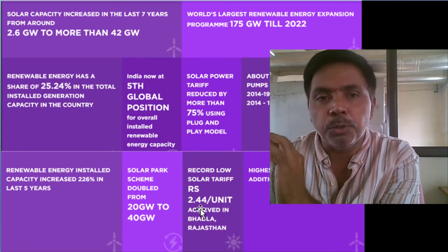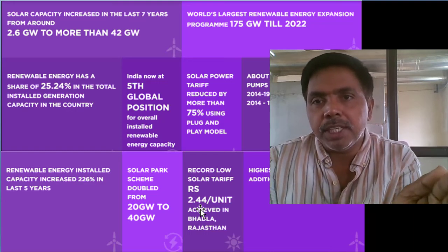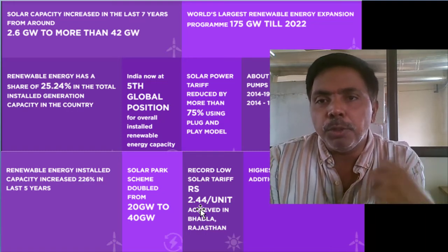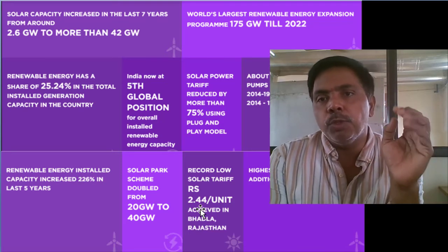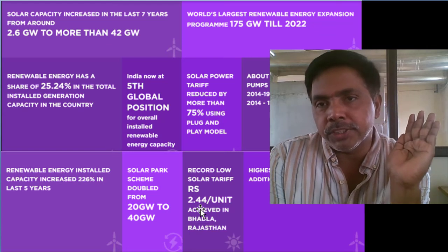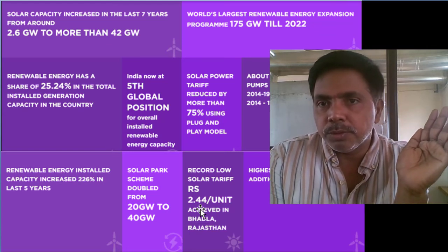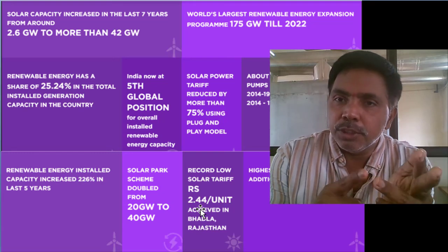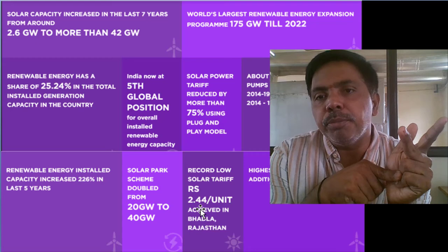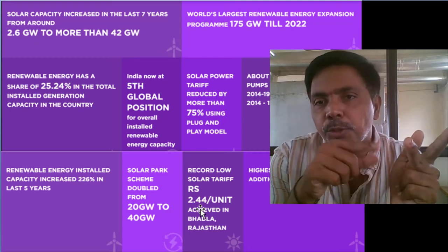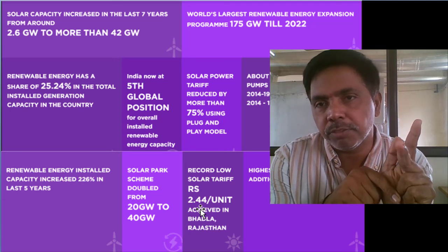Solar PV efficiency is low. Why? Because the semiconductor is unable to utilize the infrared or ultraviolet rays. It can only convert visible radiation. That's why efficiency is low. But the investment cost is reduced drastically, and operation and maintenance cost is almost eliminated.